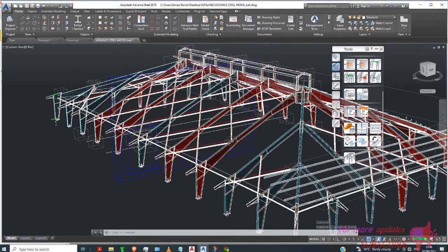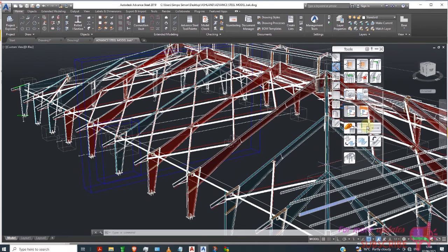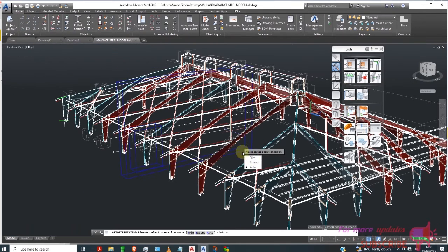So for this, you can trim system, select the objects. Then I can select even that one. I can right click my mouse and select this side, the particular side that I need to trim. Then again right click. Okay.